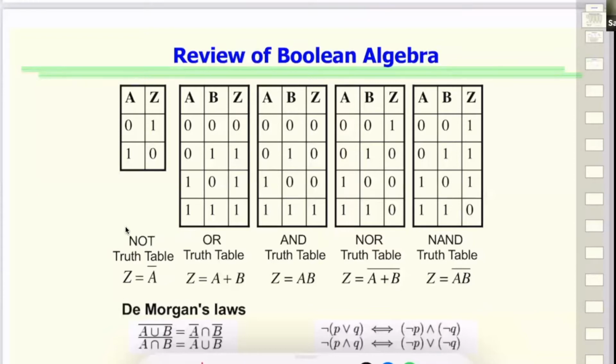For example, an inverter is where if you give it a 1, it gives you a 0 at the output. If you give it 0 in the input, it gives you 1 at the output. So that's an abstract, high level way of looking at a gate. We call them gates. And a goal here is now to connect that gate operation with the actual electronics implementation.